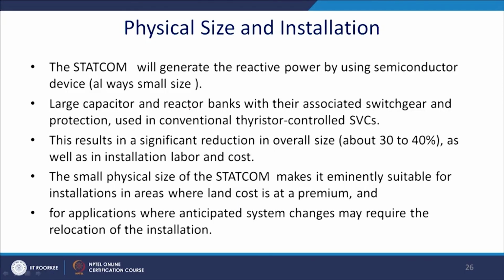And what about the physical installation? STATCOM will generate the reactive power by using semiconductors and thus has a small size. Large capacitors, large reactors with associated switchgear and protections and all those things are used in the thyristor controlled SVCs, so the system is bulky. As a result, a significant reduction of the overall size, about 30 to 40%, is possible in the case of the STATCOM. The small physical size of the STATCOM makes it eminently suitable for installation in areas where land cost is at a premium. That is also an important thing.